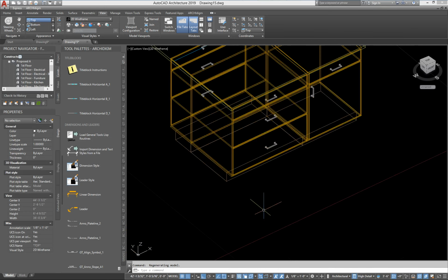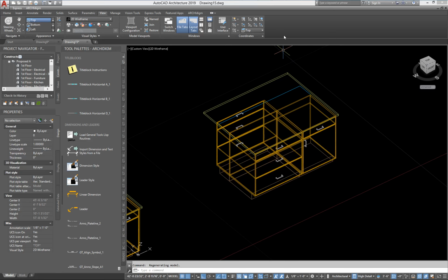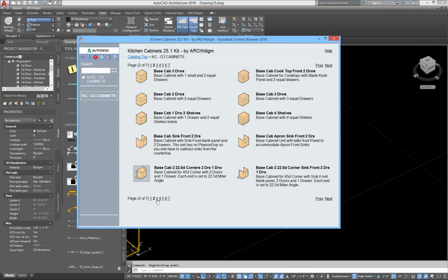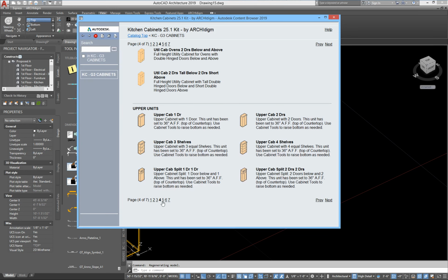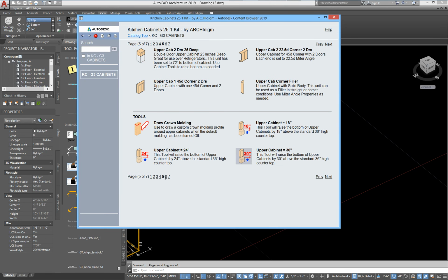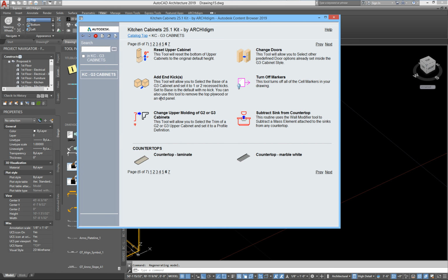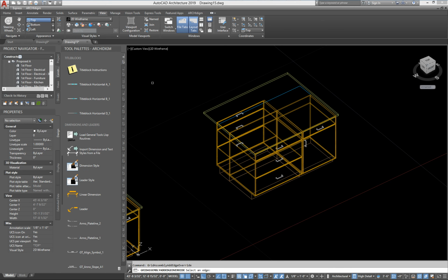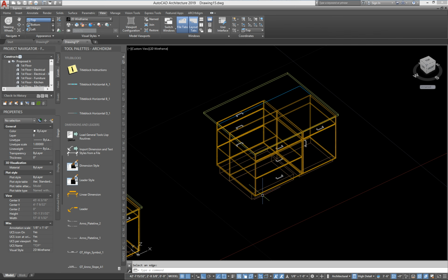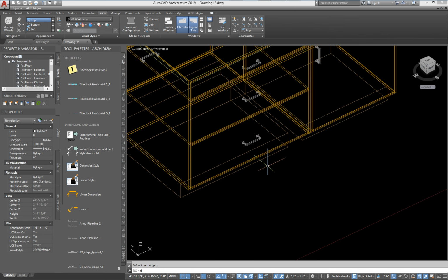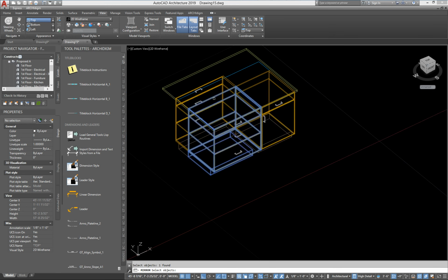Yeah, so now the kicks again. So these don't come with kicks. Let's go up here. I don't recall if there's a kick button. I don't think we added a kick tool. Oh, end kicks, there is. So insert into drawing, pick here, and then say you want to do base end kick, and OK. And it did it to the other side. That's fine. You just do a mirror. Just mirror this across the top like that. And yes, and that should work out.